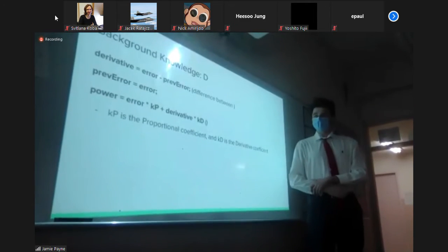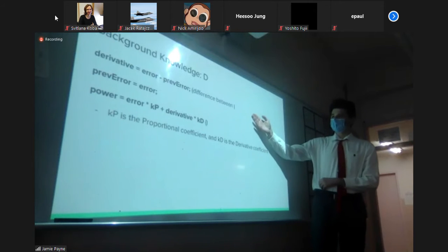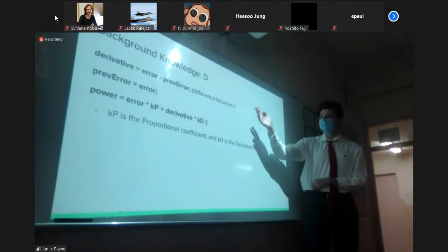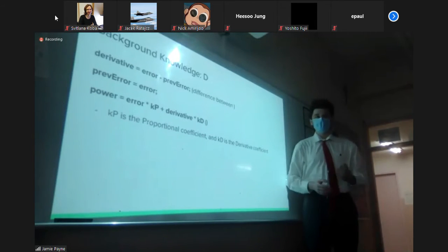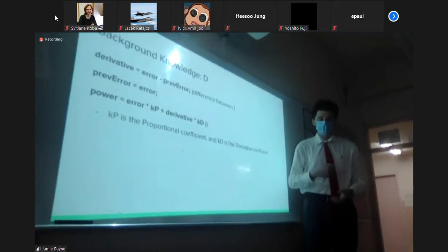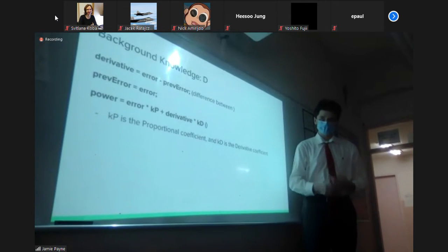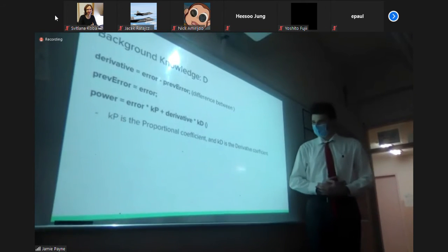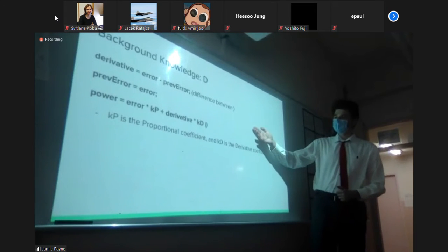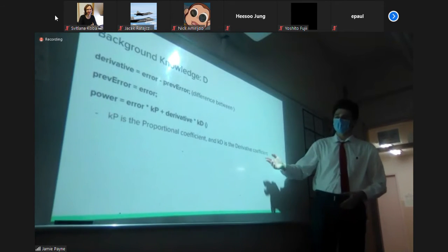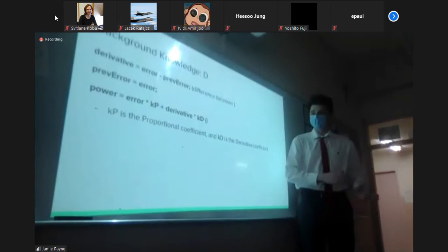How's the derivative component calculated? First, you take the difference between error and previous error, which is the error a set amount of time ago. So let's say that it's 20 milliseconds in the case of a classic robot. Then you assign the value of error back to previous error.